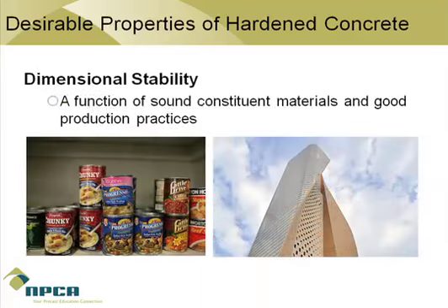Let's discuss dimensional stability. Concrete moves volumetrically, although not as much as some materials. Actually, concrete, compared to many of the building materials out there, is fairly dimensionally stable. It moves volumetrically for a variety of reasons, such as thermal change, moisture change, and even molecular change. You might have heard a term called creep. It's a situation where basically, if you put a stress on something for a long period of time, it will actually start to force a molecular reorganization in there.